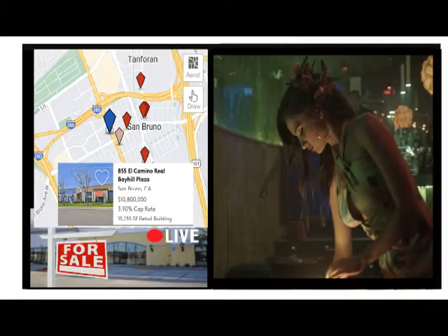Toxic fumes from this product may cause nausea and other adverse reactions. Urea formaldehyde frequently is found in older manufactured homes, where its effects may be amplified by poor ventilation. Any building suspected of having lead-based paint, asbestos, or urea formaldehyde in its construction should be inspected by a competent professional.